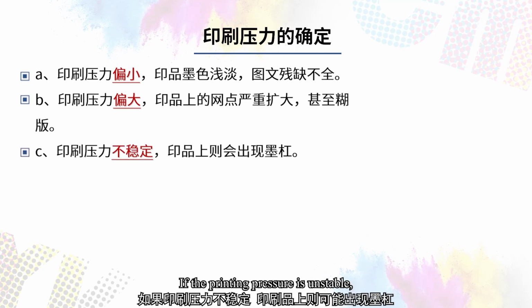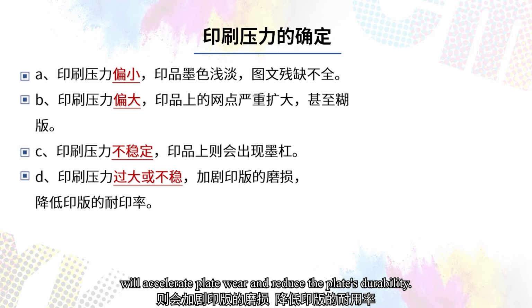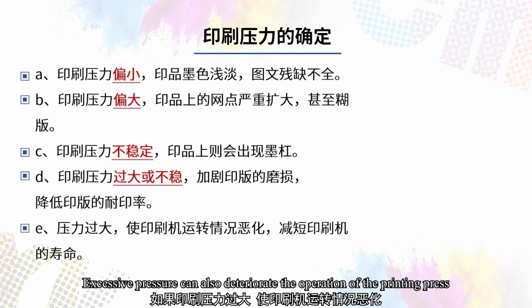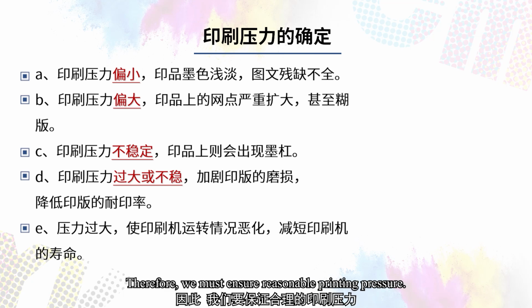If the printing pressure is unstable, ink streaks may appear on the printed matter. Excessive or unstable printing pressure will accelerate plate wear and reduce the plate's durability. Excessive pressure can also deteriorate the operation of the printing press and shorten the equipment's lifespan. Therefore, we must ensure reasonable printing pressure.